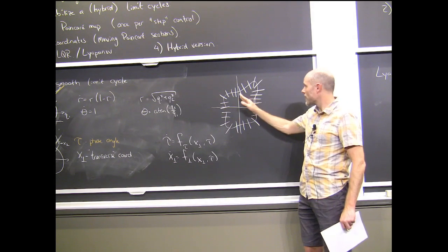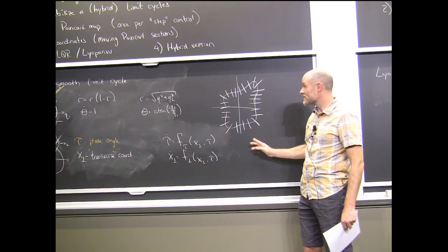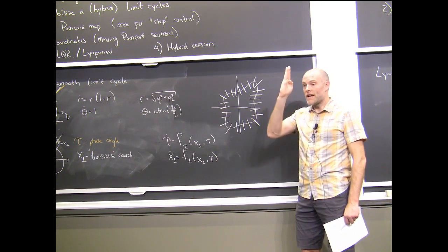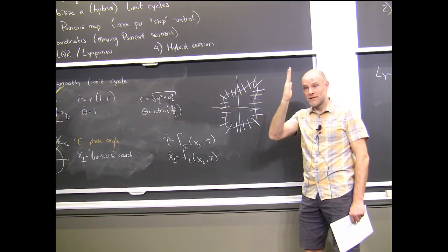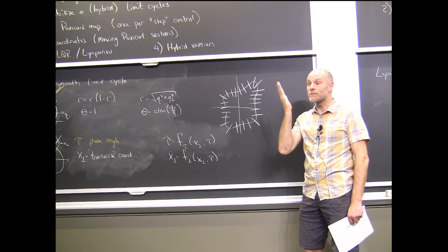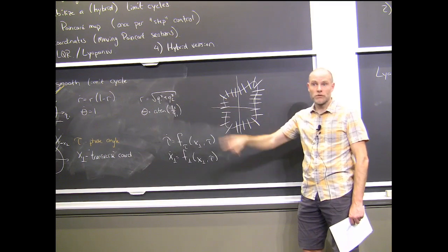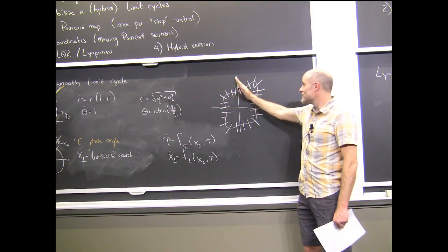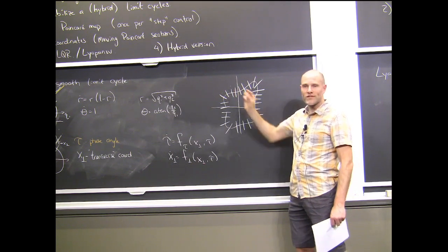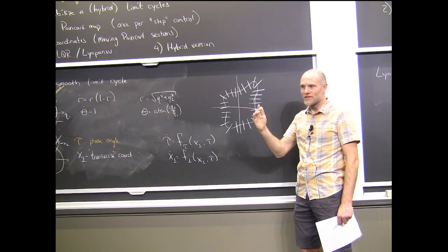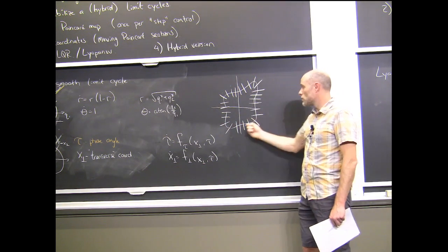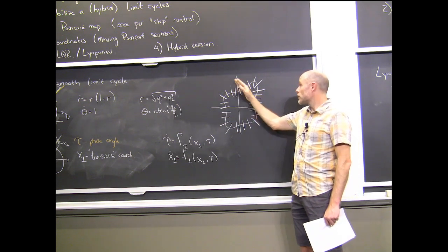Okay, so let me just try to make sure that I land why this is a useful construction. It's going to be useful for control in a second, but it's actually already useful for just making stability arguments of limit cycles. The Poincare map is amazing, but it has an assumption baked in, which is that you can come up with this P by integrating around, and very rarely can you actually get a closed form solution for P. So if you wanted to make a rigorous argument about stability, it's hard. You tend to only be able to do that numerically. Here, you can certify the conditions instantaneously along the entire trajectory. Sums of squares still has numerical limits of the solver and such, but you can do a sums of squares argument along the trajectory, and put bounds on errors and things like this, without having to solve for a closed form solution for the long-term Poincare map. You can make a stability argument around the cycle.